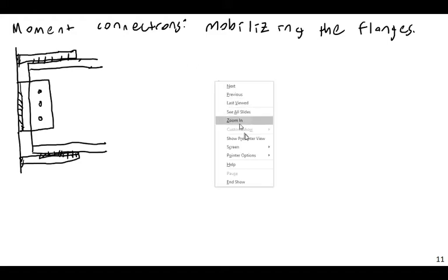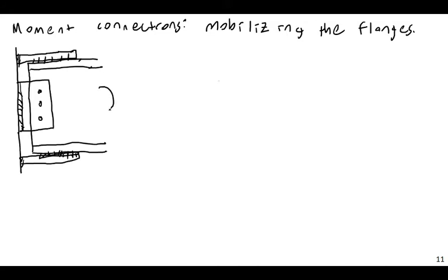So how does this work fundamentally, though? How does this connection work? Well, these two top plates, basically what I'm relying on them for is this: in order to transmit moment, you need two things. You need not only a force, but a force separated by a distance. And this overall beam is going to be transmitting some sort of moment. When I connect it here and here, that weld area provides the capacity to generate two forces, and those two weld areas are separated by a large distance, the depth of the member. Force times distance, I now have moment capacity. And that is fundamentally how you transmit moment.